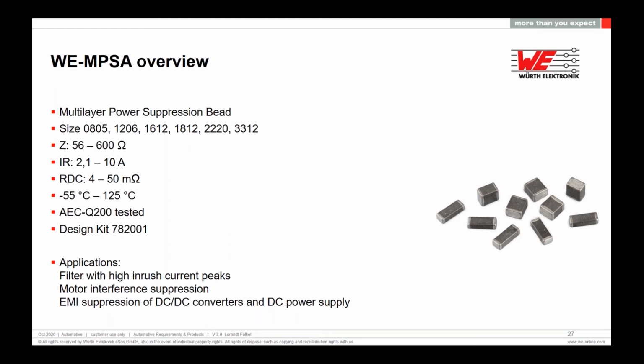So we give amps and time graphs where you can know that this ferrite withstands this load dump test or this inrush current when you start your computer or your electrical motor, and you have a nominal current like 10 amps and you can apply up to 20 times higher inrush current. And if you see in the graph this is more like 100,000 times, then you can sleep safely and well over the night because it will not be damaged.